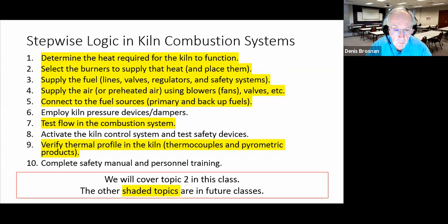We probably won't talk much about kiln pressure, but nevertheless, we know that when we inject these gases into the kiln and the heat is released, we're going to expand the gases quite a bit, and that develops the pressure within the kiln. In a lot of cases, we want to control that pressure in the kiln, maybe have a little bit higher pressure in the kiln to encourage heat transfer.